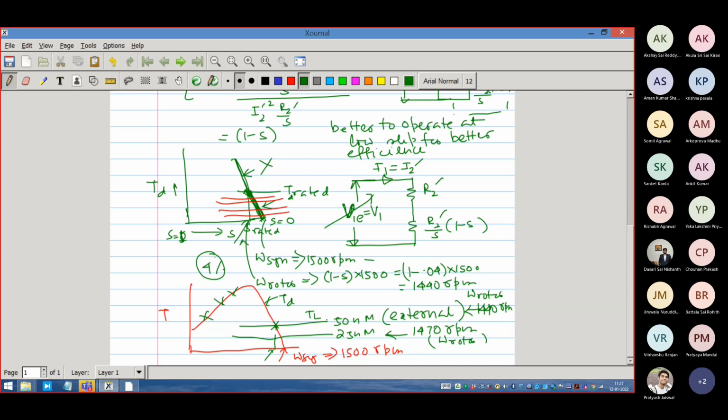You say that is my choice, but the supply voltage will not dip, right? So here also the analogy is like that. Here also the constraint will be, they will be saying the mechanical speed should be what I want, but I should have the option of varying, demanding different amounts of torque from the machine. The mechanical system would ask for it. That means the characteristics should be speed unchanged, torque changing, which in the original form is not possible.